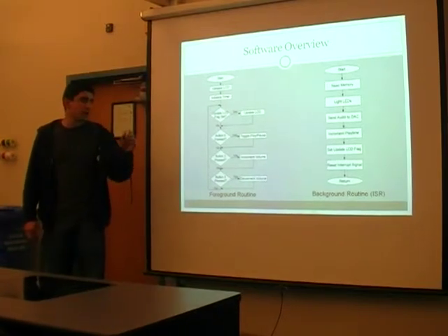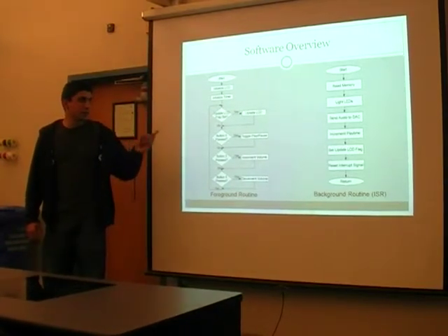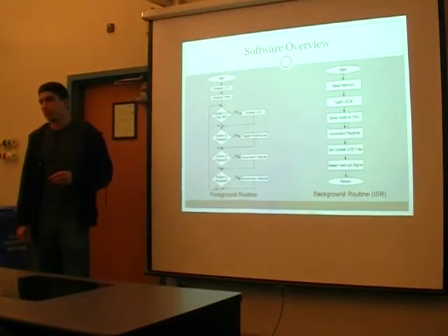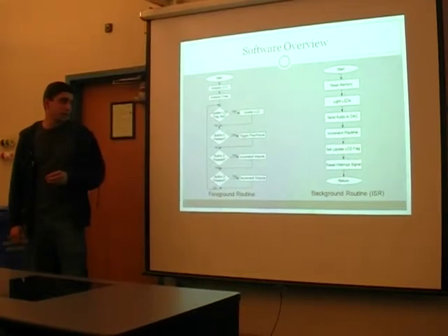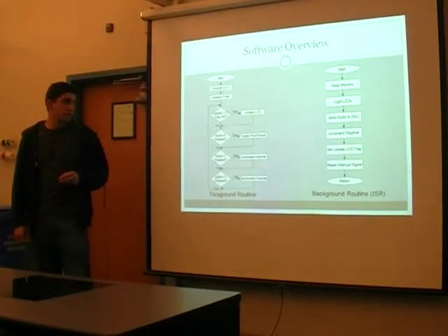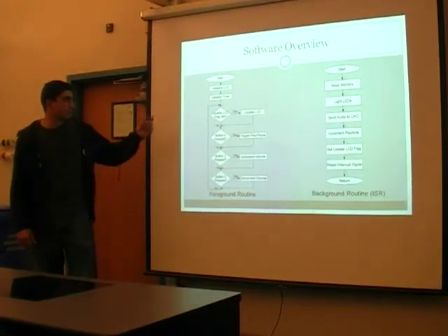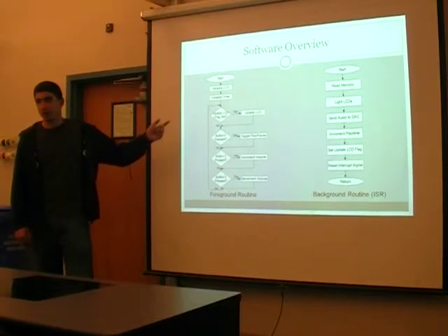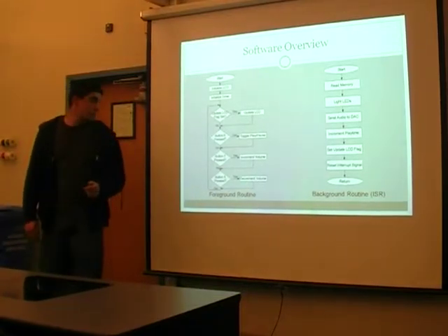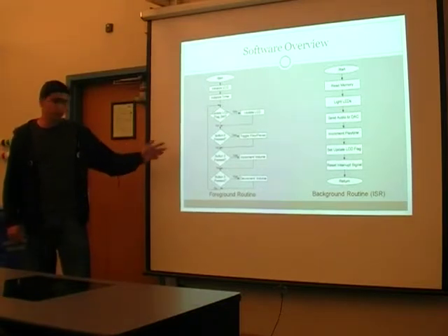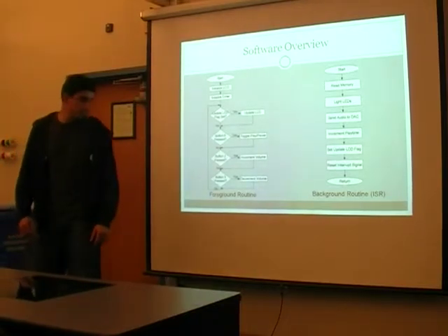After the LEDs are lit, the audio is sent to the DAC, and then we increment the playtime with millisecond accuracy, update the LCD screen, and reset the interrupt signal. Then in the foreground, we check if we need to update the screen, check the buttons for play and pause, and then increment the volume.